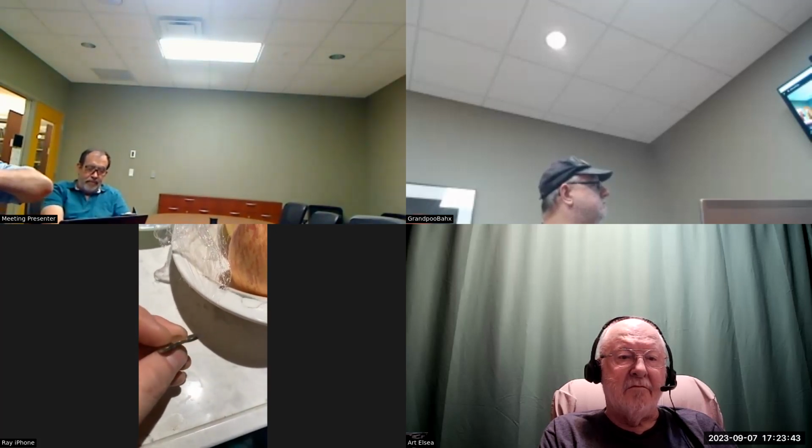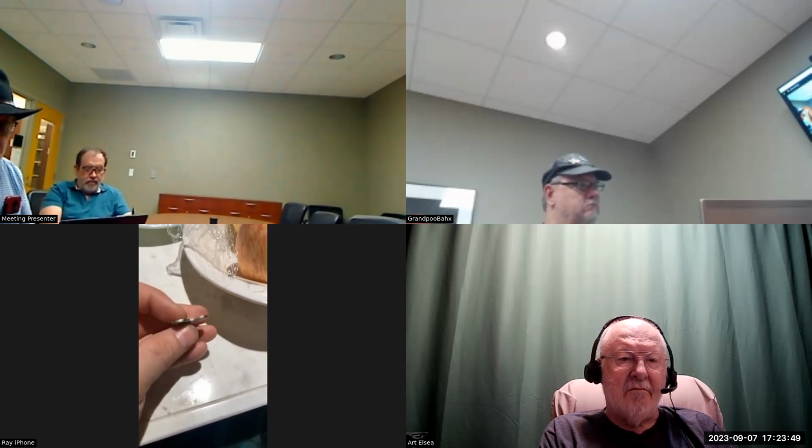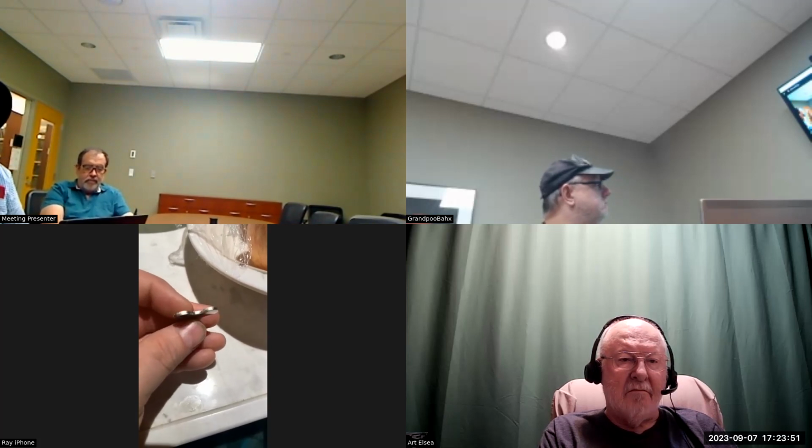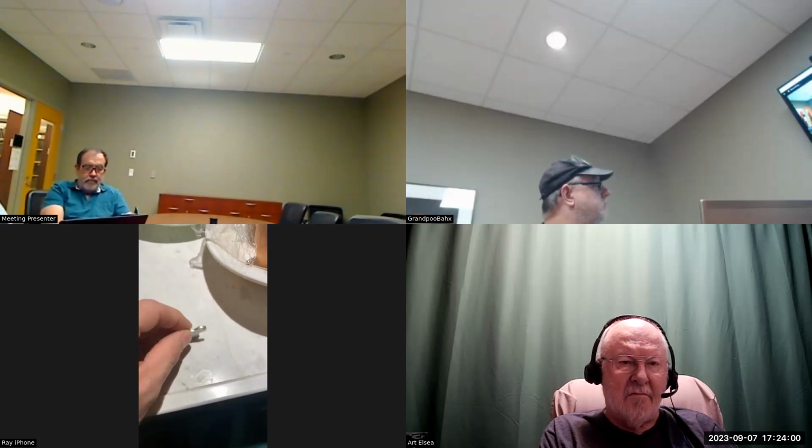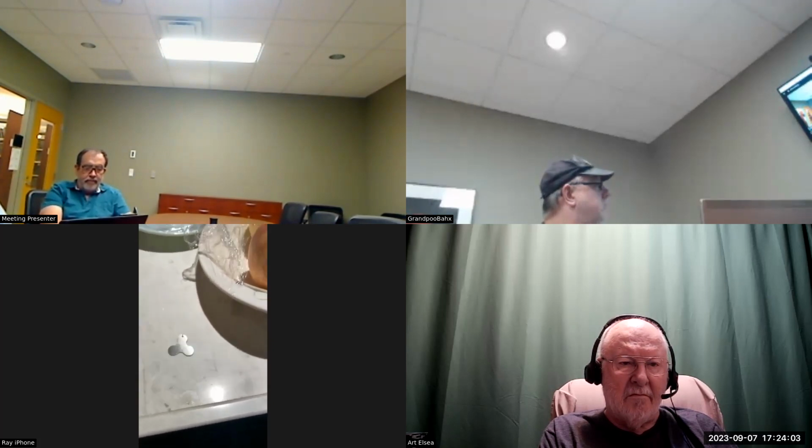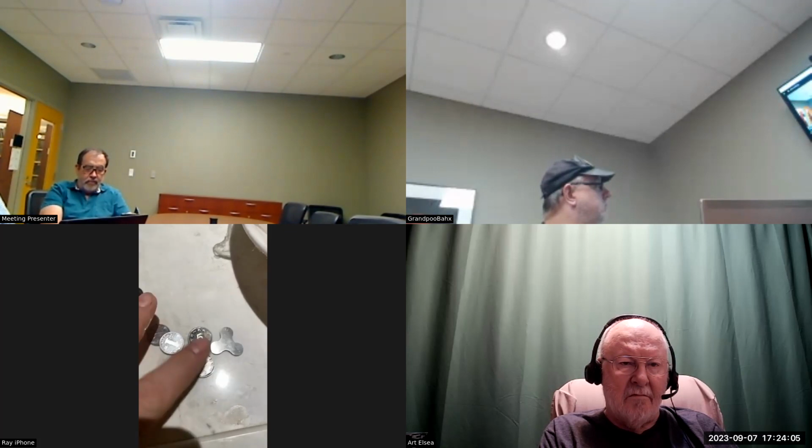Well, today I did get to play with a laser that is the same as what I've got at my shop, the same wattage and everything. They were using nitrogen as a cleaning aid or as a control environment gas. The thing about nitrogen is that it leaves a nice, pretty, shiny edge. And it cut through this, which is about the thickness of a quarter. And these are obviously not quarters.